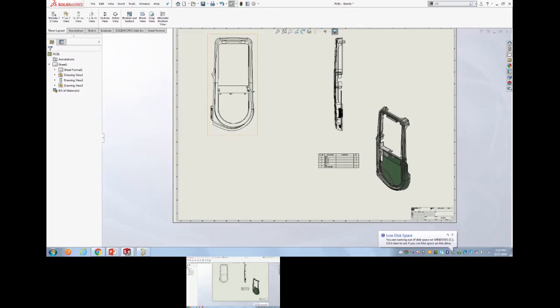Up to you. So heatsink, remember, now we can bring, like how we brought the enclosure and the placement barrier, a heatsink is a part in the mechanical. You can bring that heatsink, add your heatsink to the PCB and push it over. And then Robert can define the holes, where it goes, how it needs to go. He's not going to move it, because if it needs to go somewhere, then he's just going to say, okay, I'm going to drop the holes here, I'm going to do my stitching vias that need to go there, and push it back over to you.